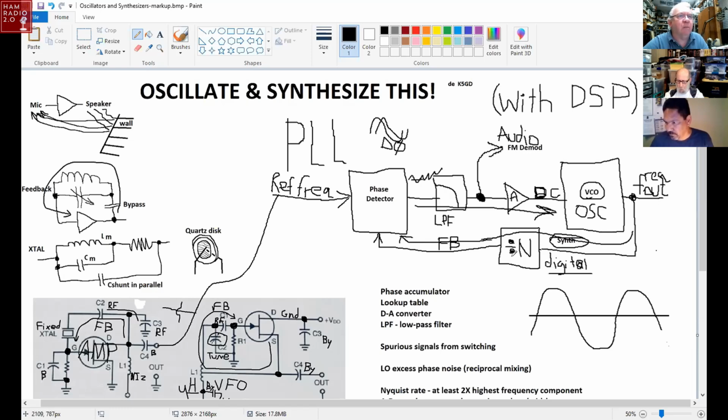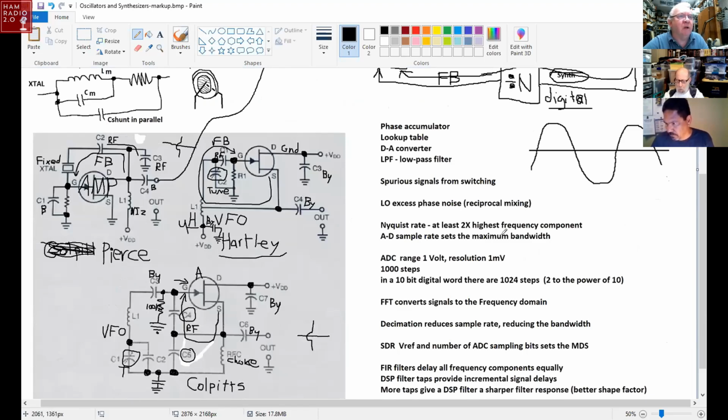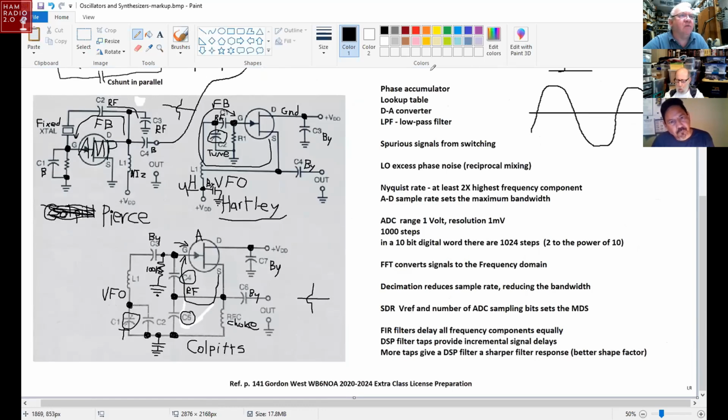Now let's talk over here about the DSP functions. Now you guys are fortunate because in 15 or 20 years, instead of just recognizing the functions of DSP circuits, you'll have to be recognizing bits of computer code that perform these functions, because every one of these functions can be done, I guess with one exception of a low-pass filter. That's still analog, although you can make low-pass filters in a DSP. It's called an average. But most DSP things now would bring out a pin for a low-pass filter and then take it back into the DSP processor.